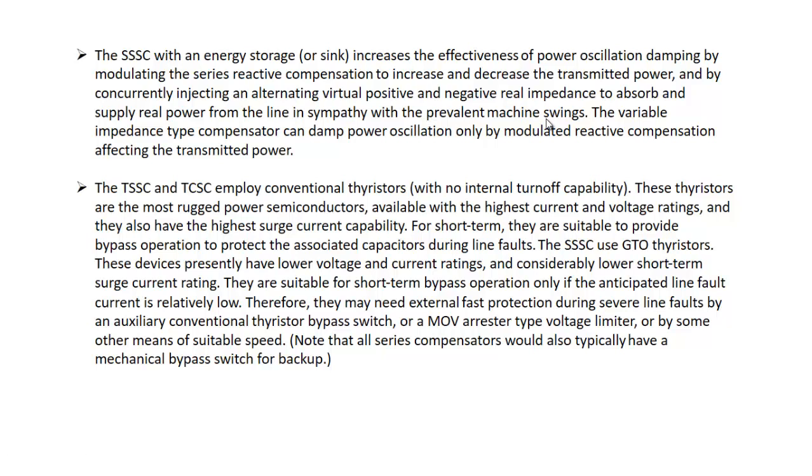When there is a change in the electrical power, or a change in the load, a new steady state for the rotor has to be established, and the new steady state will be established after having some oscillations about this steady state point. When you supply some electrical power before it settles to the new steady state, these oscillations will be damped.